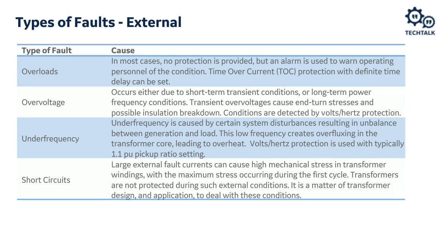Excessive loading means high current. Typically, the transformer would either be overrated to account for higher than usual loading, or otherwise it's often acceptable to run transformers slightly overloaded for some period of time. This is typical during summer months when everyone's running their AC at the same time. So usually we don't want our transformer relay to trip on overload.